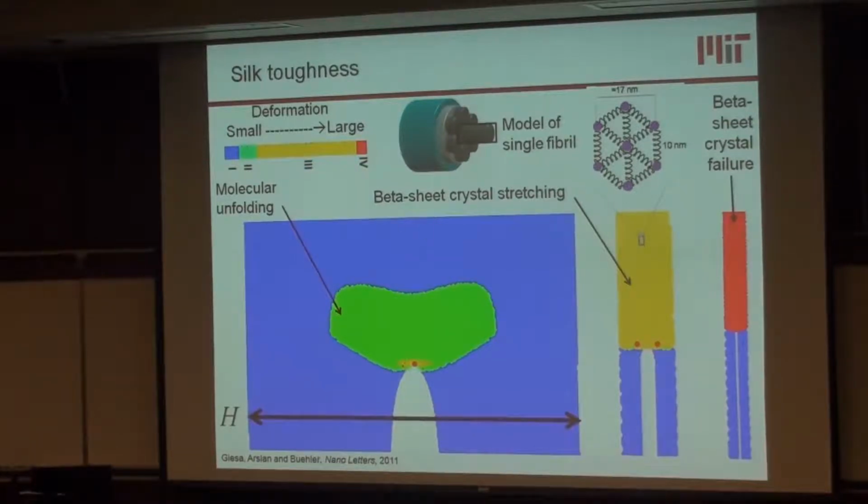The crack will make the fiber become two fibers. But if the fiber is thin, the crack will be difficult to propagate, and the deformation energy will go through the entire rest of the material. That explains why spider silk is usually very thin, because if it's thick, it will easily branch and become fuzzy, and it will not be able to support loading in one single direction.